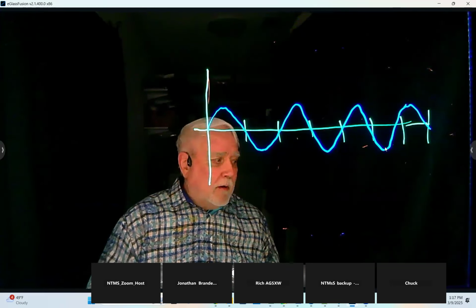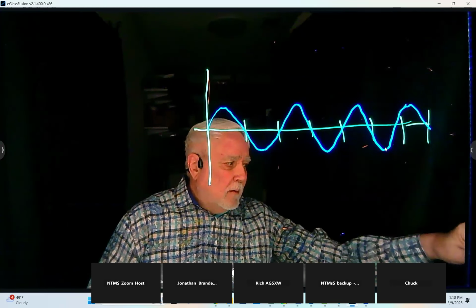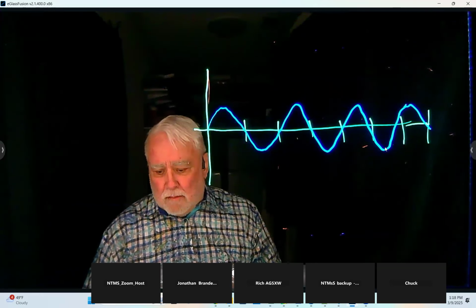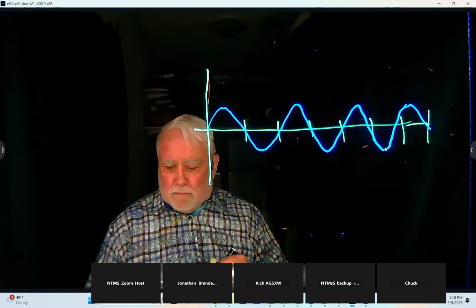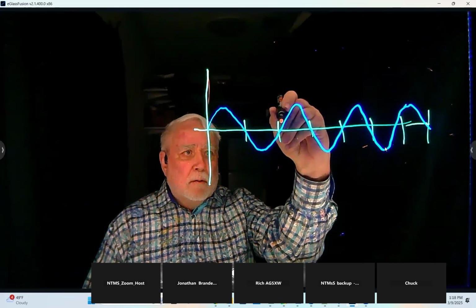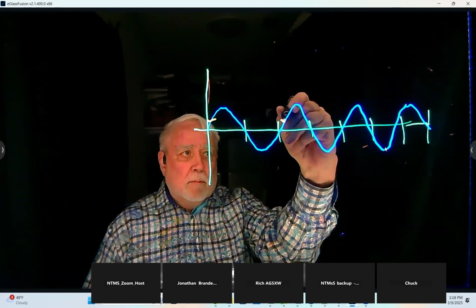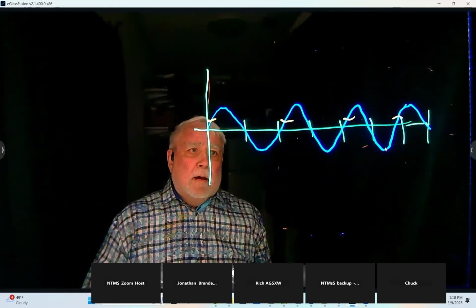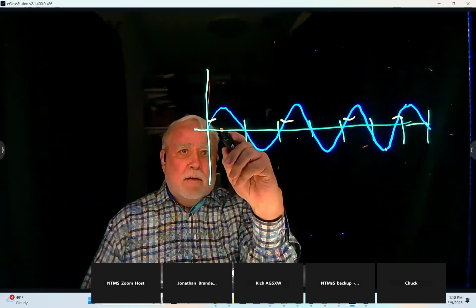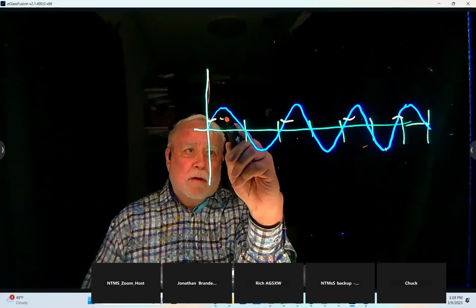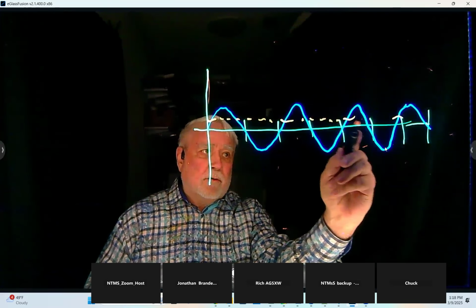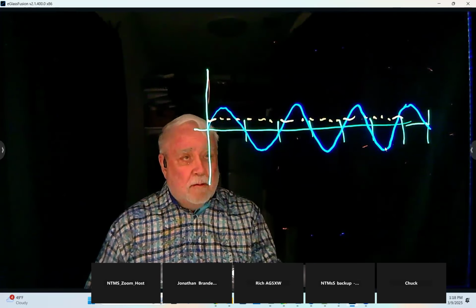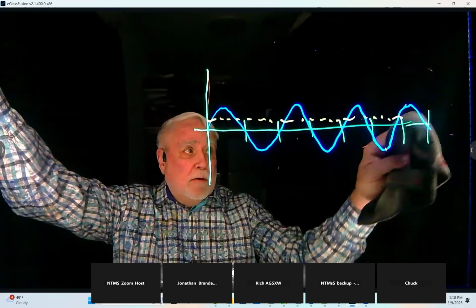And then we've got to take samples. So if we take these samples at the same frequency that we've got in the signal, that would put the samples, let's say the first one's there, the second one would be there, third one would be there, fourth one would be there. Now, the problem with that is if you're going to recover the signal from those samples, that's not looking too good, because this is what you'll reconstruct, which is not the original signal. So this is highly undersampled. I don't think anybody would have any problem understanding that.